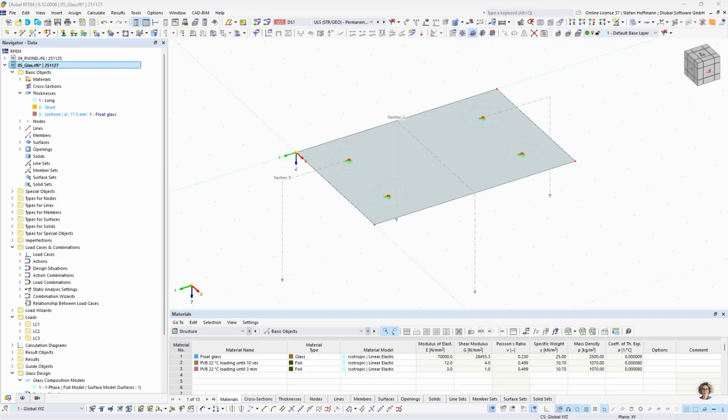But in the next chapter, 7.2.2, in the case of an unfavorable shear coupling, e.g. in the case of restrained stresses, full shear coupling must be assumed. So you usually have to consider both states doing your calculations.